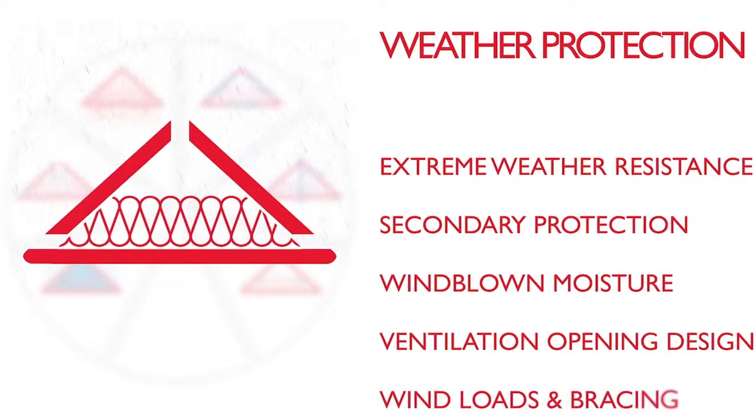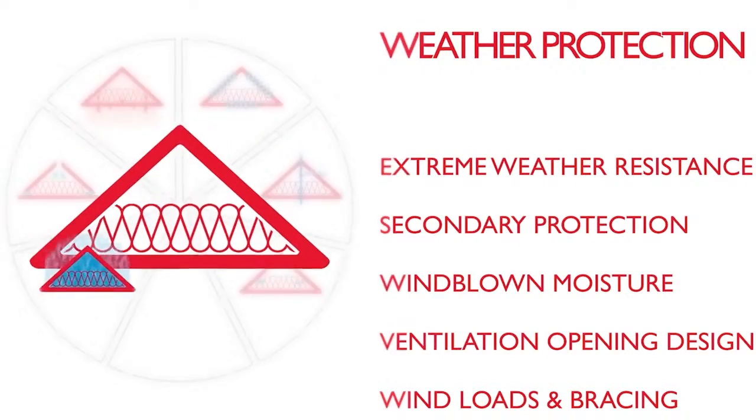Ensuring all parts of the roof structure can properly resist wind loads without damage is also important. As with many aspects of roof design, this may have a knock-on effect on other parts of the specification. If, for example, a particularly exposed location requires the use of additional wind bracing or sarking boards, or necessitates changes to the specified outer covering, this may require additional or different condensation control measures.